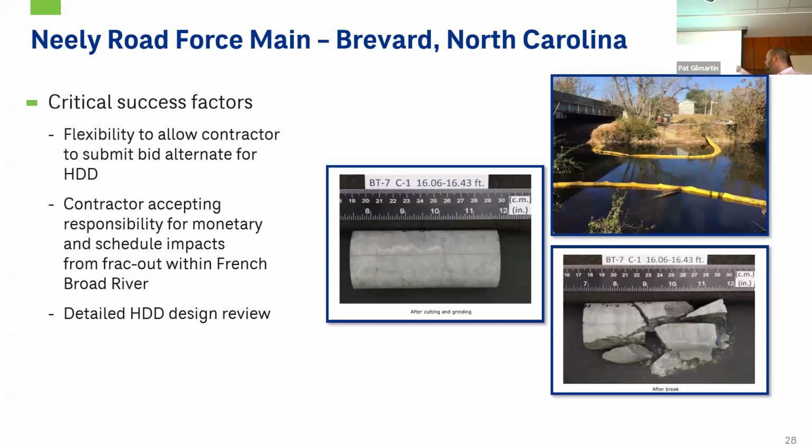And so similar to what I was talking about with the booms earlier, we did end up getting a frac out in the French Broad. And so the interesting thing about that was we made sure that that was in those contingency plans, and we included that in the specifications. And the contractor had them on site and was able to contain the spill within 10 minutes.